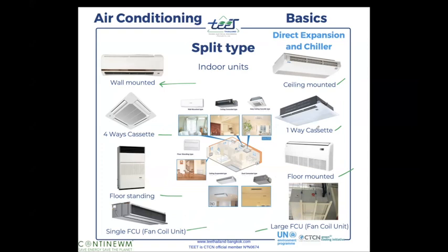All of them can work with direct expansion, the refrigerant fluid directly, or with the water from the chiller. They have different references because the evaporator coil is different, because you don't have the expansion valve with the water, obviously. You just have the regulation valve, but they look exactly the same.